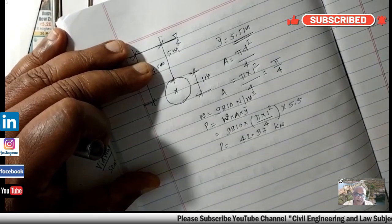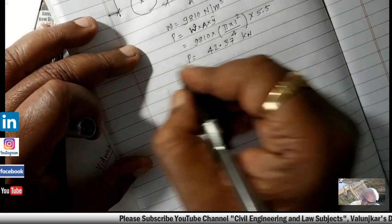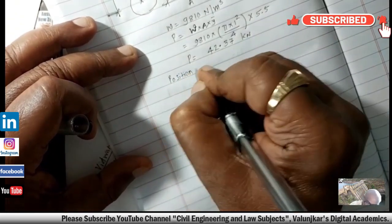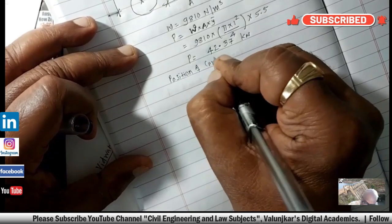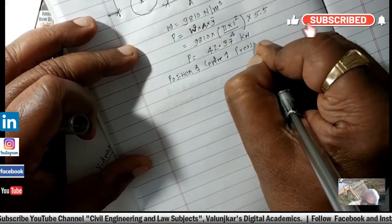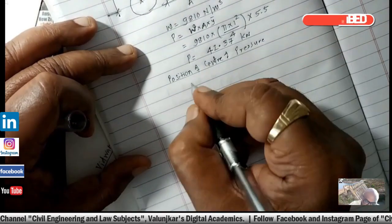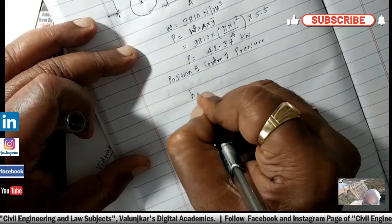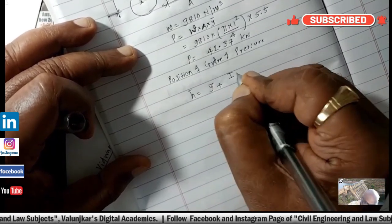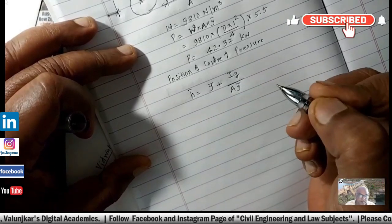Now we want to find out the position of the center of pressure. Lamina is vertically immersed, so the formula will be H bar is equal to Y bar plus Ig upon A Y bar.